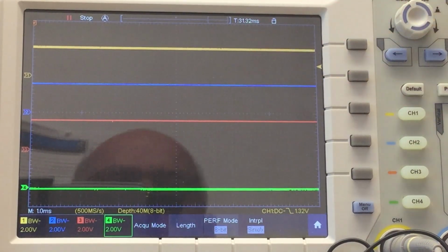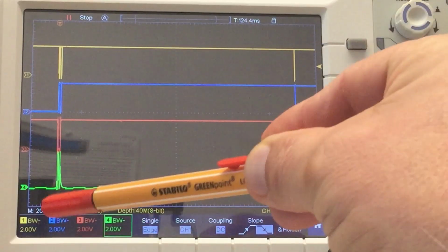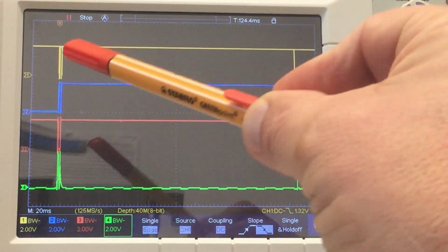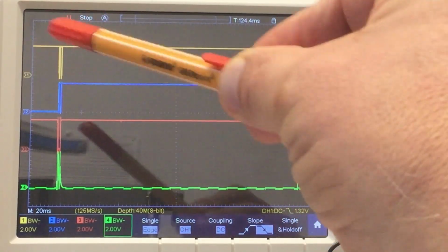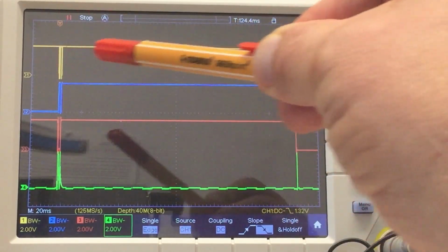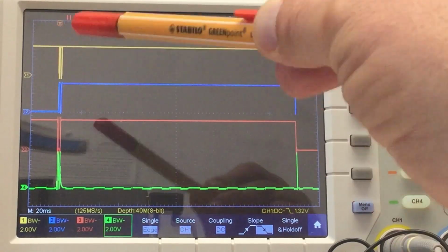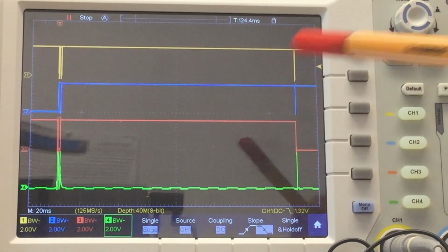operation, so just reading. I am capturing here on a much larger 20 millisecond timescale per division, and you see after startup, the error handling, the total 5 SPI transactions, and after I reset that error flag, the power down, low power warning flag, the next transaction is much smaller.